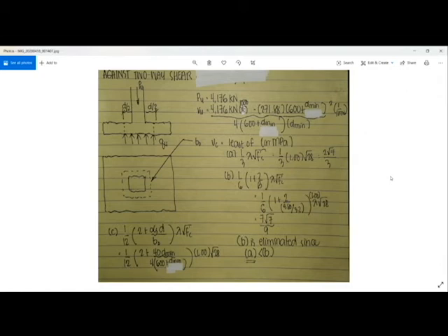So from our code, our Vc is equal to the least of the following: formula A, formula B, and formula C. Please ignore formula B because I made a mistake of using formula B. Since our column is square, the longer and the shorter dimensions are just equal, so there is no formula B. Either I just use formula A and formula C only.